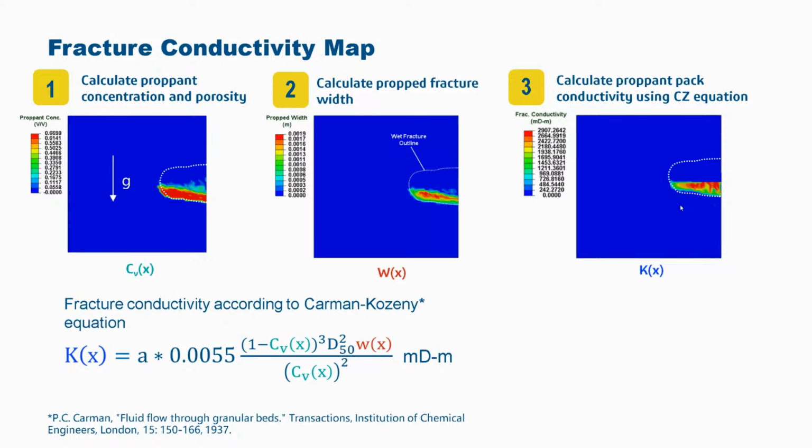As I had mentioned a couple of slides ago, in an enhanced geothermal system, you have an injection well and a production well. These two wells are connected by a fracture. And this fracture is filled with proppant, and the conductivity of the proppant is going to determine the extent, or the ease, of hydraulic communication between the injection and the production well. So basically, these simulations allow us to capture some of the very intricate responses of enhanced geothermal systems that ultimately determine their efficiency.